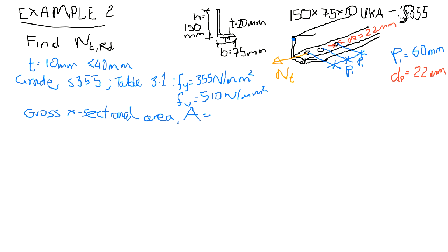Then we take the 65, from here out to the end, multiply by 10, and add the two together. But actually there's a little fillet around the corner here, so there's a little bit extra area, and a little drop-off here and here. So that wouldn't be exactly the cross-sectional area.